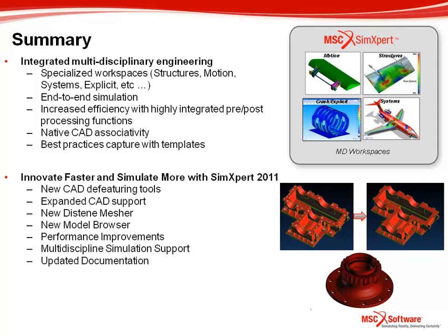Some of the new features that we covered in this presentation were the CAD defeaturing tools and CAD support, and the new Distene mesher, allowing you to significantly speed up CAD cleanup and generate a high quality mesh. The new model browser and performance improvements allow you to manipulate models faster, along with improved Nastran and CAD IO performance.